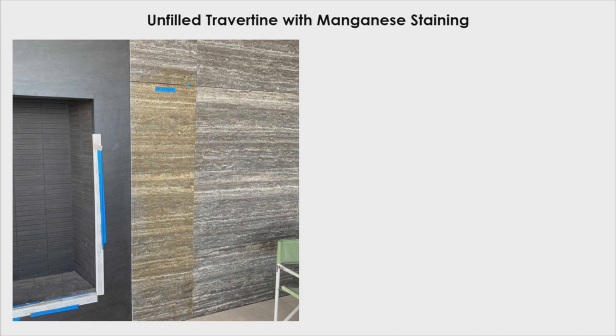So, we did investigate. We removed some stones. We saw that they used a thin set adhesive to bond to a plaster substrate, actually to a membrane over a plaster substrate. And they had some mechanical anchors attached to it as well. And the stone had a resin backing. So, it didn't seem anyway that the moisture would have been migrating from the back to the surface.